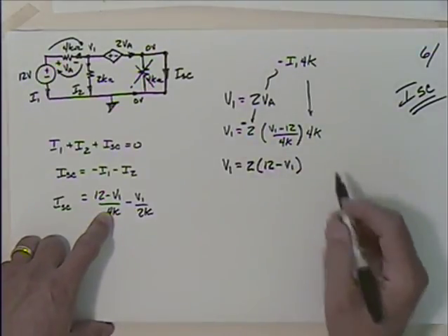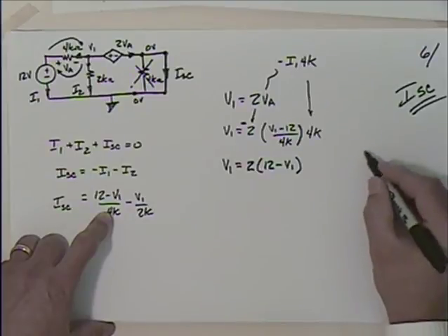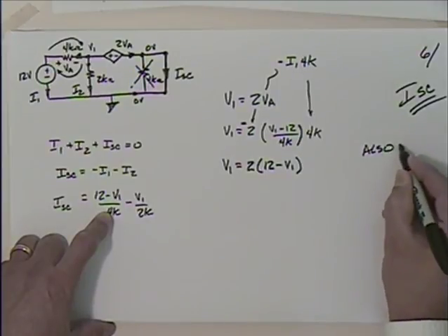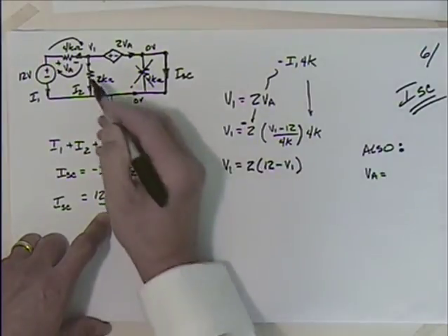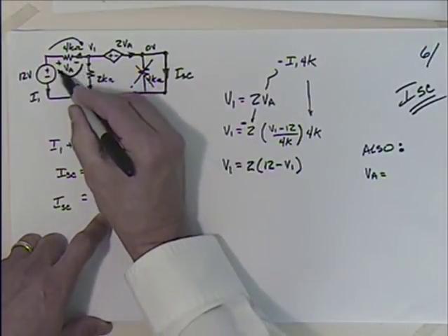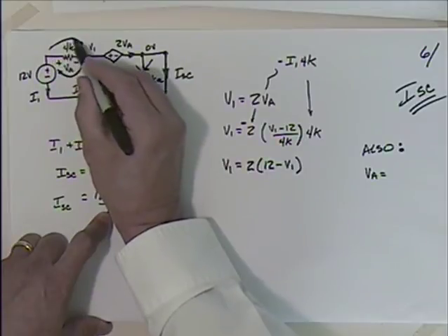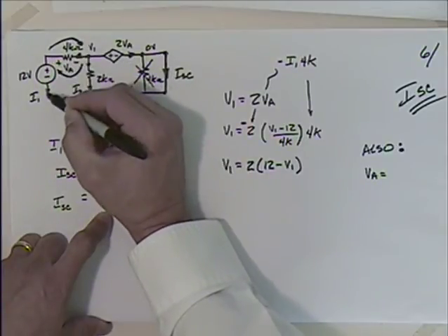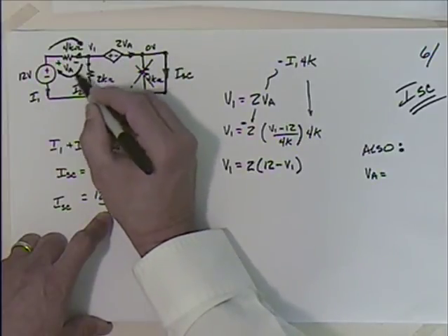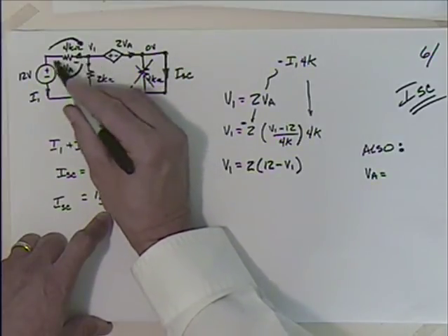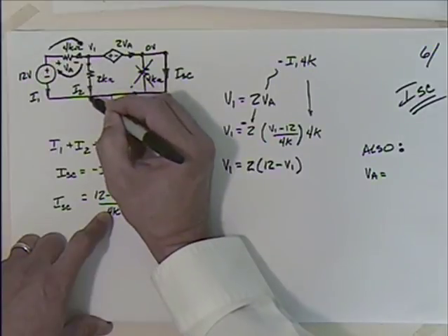Well, I kind of made a big deal out of nothing there, because you could also just say we could come over here and look at VA, couldn't we? VA is that arrow there. I was finding this voltage to try and define this current I1, because I wanted to find the voltage potential opposite the direction of the current, but this is VA, so how do I get from there over to there? Well, I subtract V1,